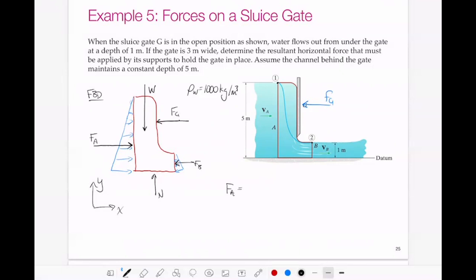So if we look at this problem as if it's a mechanics problem and we have a distributed load, how would we calculate the equivalent force of a distributed load if it looked like this? And we knew the pressure would be equal to H times gamma. Yeah, so good.